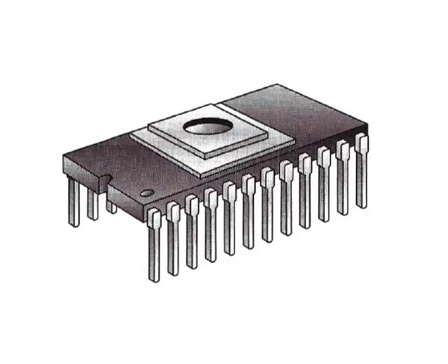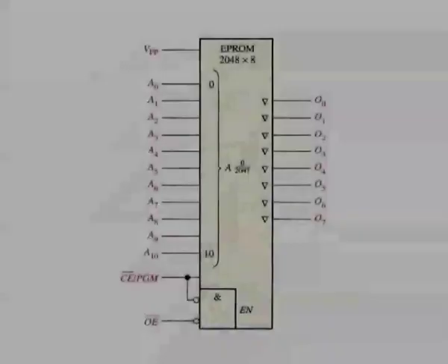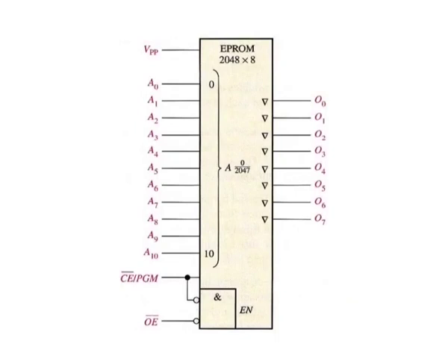Erasure is done by exposure of the memory array chip to high intensity ultraviolet radiation through the quartz window on top of the package. The positive charge stored on the gate is neutralized after several minutes to an hour of exposure time. A typical UV EPROM is represented in the figure by a logic diagram.